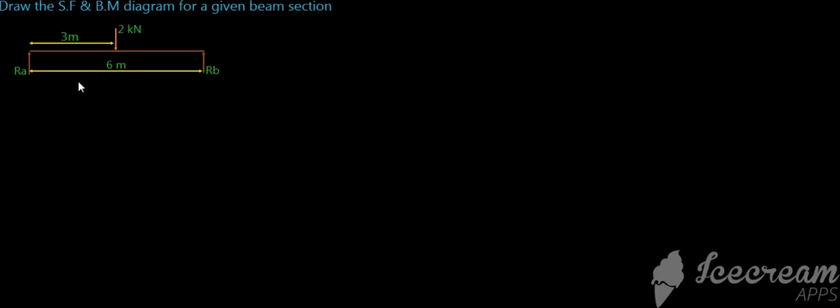Before starting the calculation, I must say the sign convention. Here is my sign convention: upward forces plus, downward forces minus, clockwise moment plus, anti-clockwise moment minus. These are the sign conventions relevant to this problem.